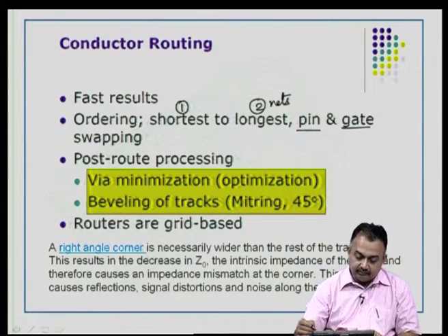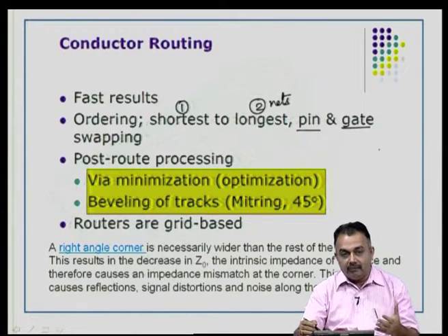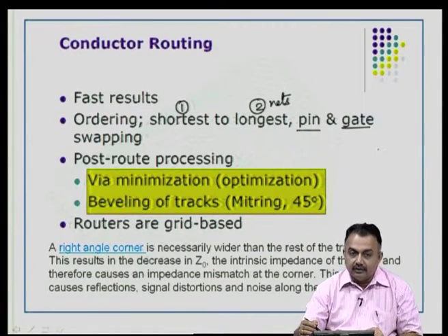Once the routing is done, it is going to take a long time if it is a very high dense board, and your CAD program is not going to do 100% routing. So, like you have done some manual placement, you also have to learn to do manual routing process for your interconnects. Okay. So, you should not depend entirely on the power of the tool to complete 100% routing. It is very difficult to get 100% auto routing.